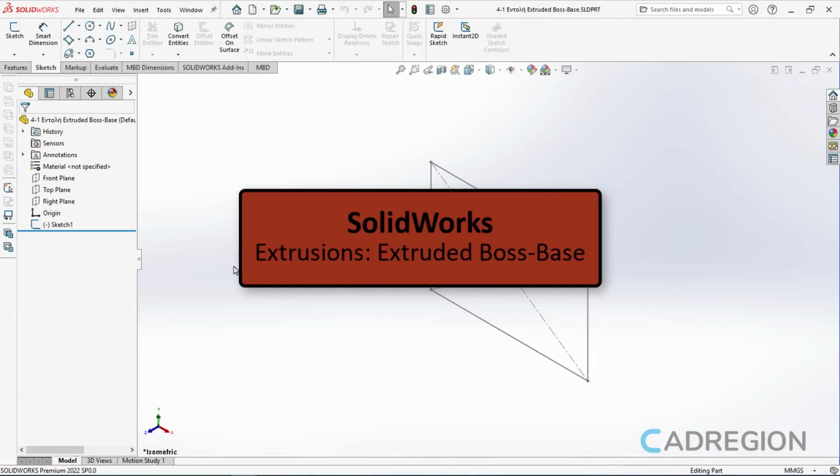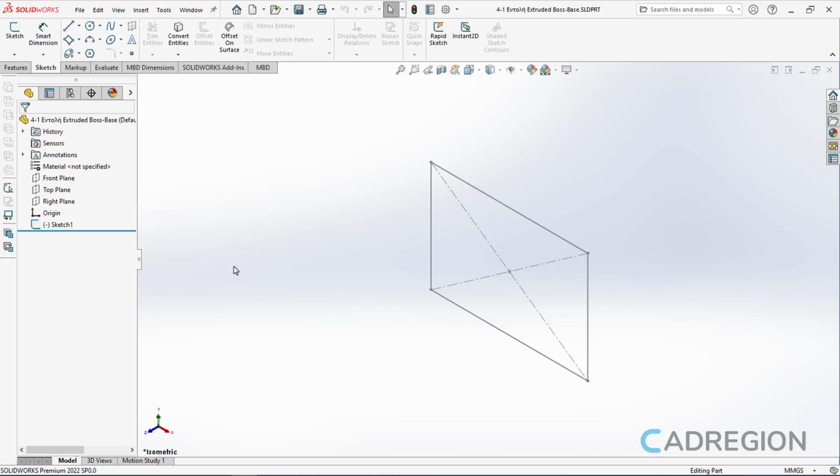In the previous lessons, I showed you how you can create 2D shapes in Solidworks and edit them. In the following lessons, I will show you how you can finally create 3D objects and how you can edit those objects. At this point, I should mention that you cannot create a 3D object in Solidworks if you haven't created a 2D profile beforehand. So before you start creating 3D objects, you have to create the 2D profiles you need to extrude.